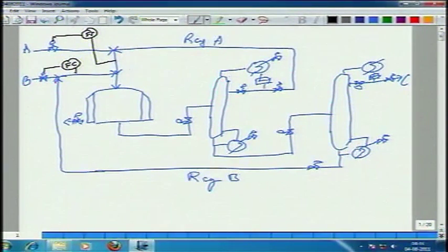that takes care of the stoichiometric feed balancing problem. Okay, and the rest of the control system, you have to have a temperature controller here, because if any A leaks down the bottoms, it is going to contaminate your product C, right. So, maybe what we can also do is, we are measuring the impurity. You see, you will always have in an operating plant, product quality is always measured, no matter how hard it is to measure.